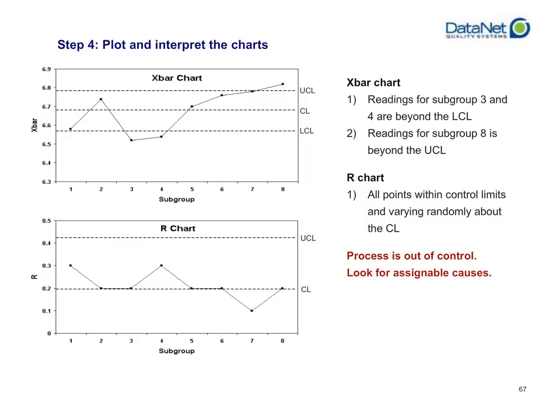These control limits came from your data. You calculated these control limits. It's actually based as the actual voice of your process. And since it is out of control, it's actually showing that there is something that is statistically significant that you're going to want to investigate.